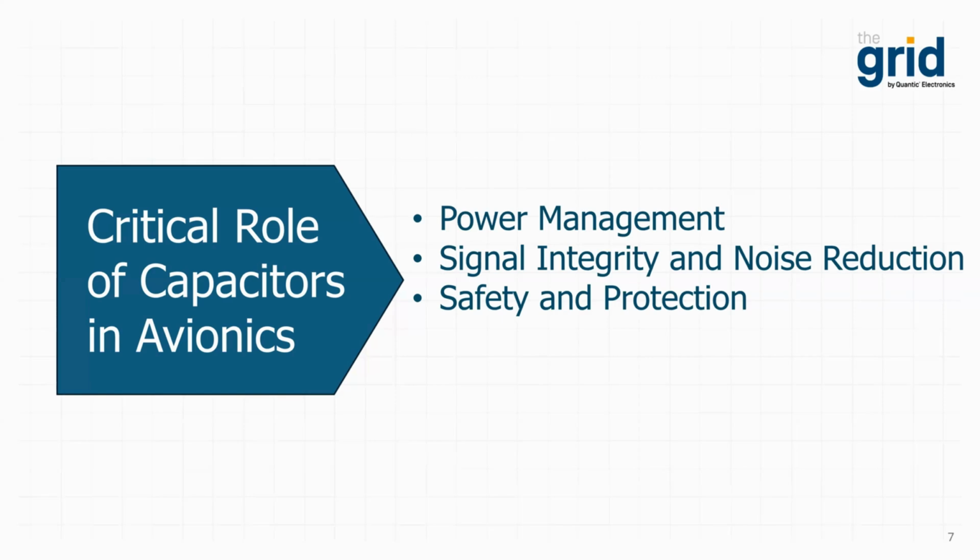Additionally, capacitors help filter out electromagnetic interference, otherwise known as EMI, and high-frequency noise, thereby protecting sensitive avionics components and enhancing overall system performance. Specifically, capacitors provide power management, signal integrity and noise reduction, and safety and protection. Now, let's take a closer look at each of these functions.